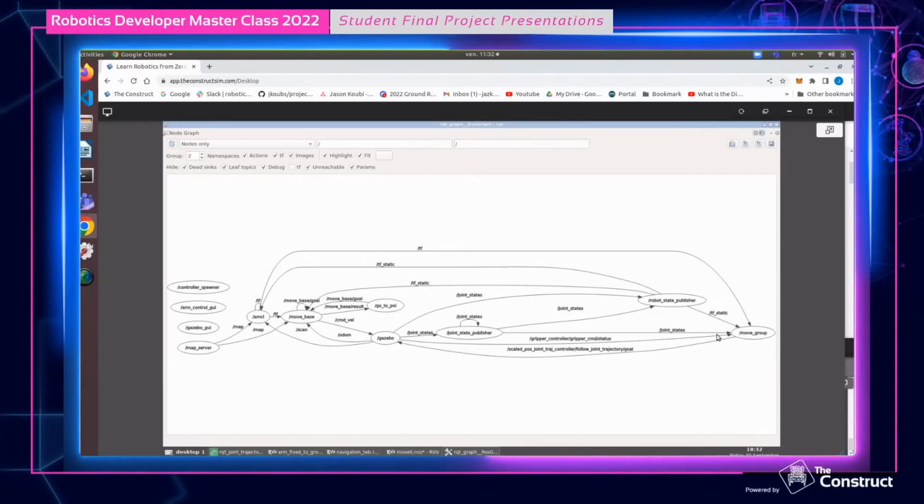A little bit like I did with the cmd_vel, which allowed the communication between the wheel motors and ROS. I've used rosserial, so I think I can use rosserial to communicate between my arm motors and ROS topics. So I need to allow this communication first. The same for the gripper.